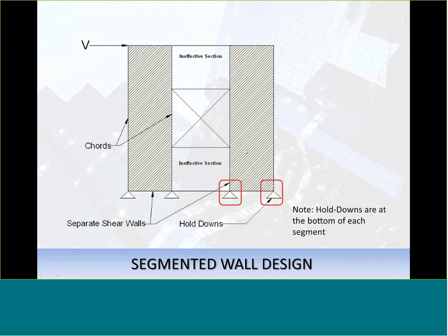One of the things when you do segmented design, you'll note you get hold downs at the bottom of each segment. So you'll see that I have hold down listed on each side of that chord. The chord is the outside element, so you're going to have a chord on each side of your segment, and underneath each chord you'll have a hold down. So when you design it as segmented, you're going to get these internal hold downs.